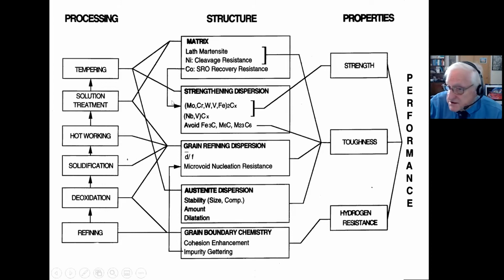And from this system perspective, we can identify and prioritize the structure, property, and process links for which we want to build predictive models. And I should emphasize that what the CALPHAD databases are allowing us to do is, instead of settling for superficial correlations, we really can take mechanistic understanding and make it quantitative in a system-specific way. So for the first time, we can really use our scientific knowledge to engineer with.